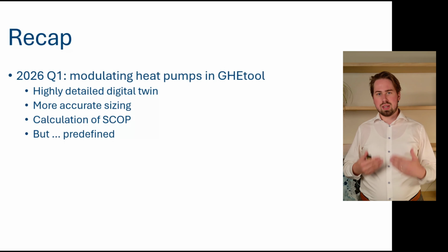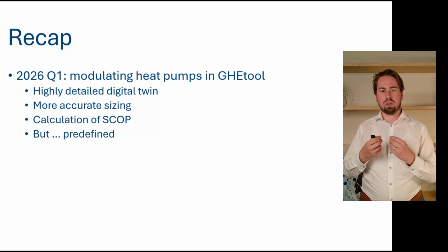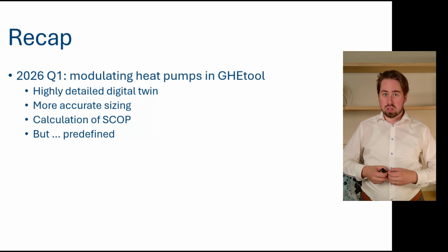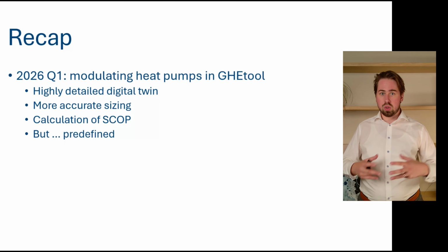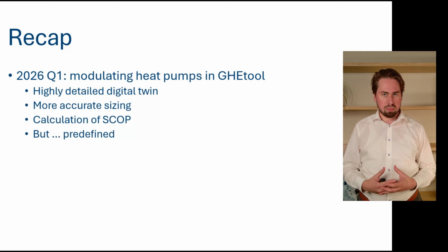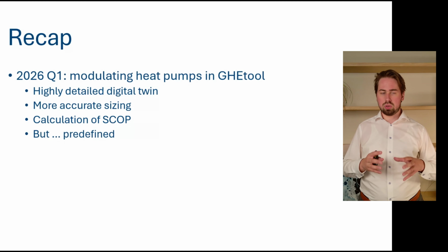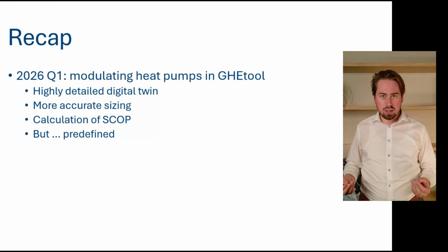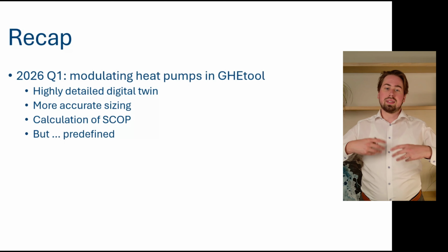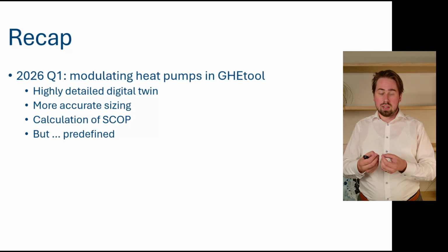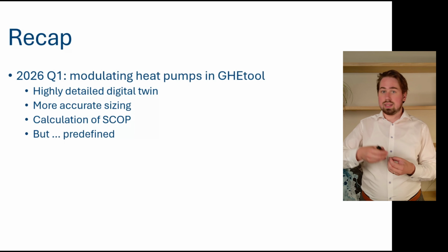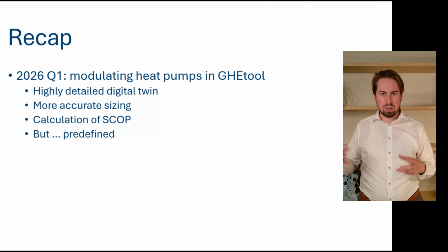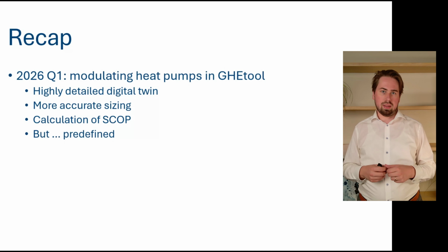added the option to simulate with modulating heat pumps inside of GHEtool. So instead of just simulating your bore field, you will now have the option that you can simulate your bore field together with your ground source heat pump. And the way we did that is we worked together with manufacturers to get more than 80 measurement points of each machine. And by doing so, we can create a highly detailed digital twin that was able to predict the efficiency of the heat pump at every part load condition and every combination of source and emission temperatures.